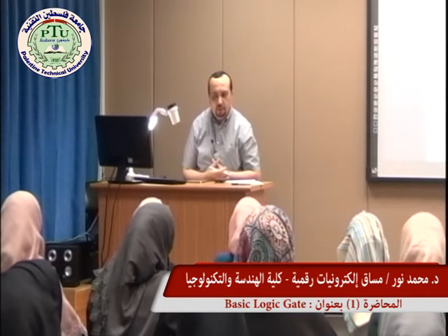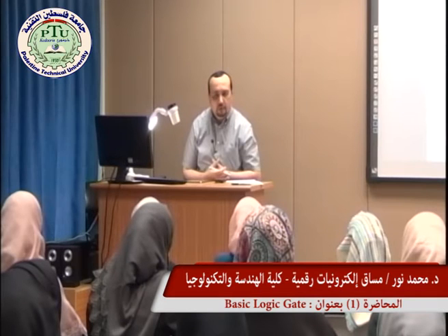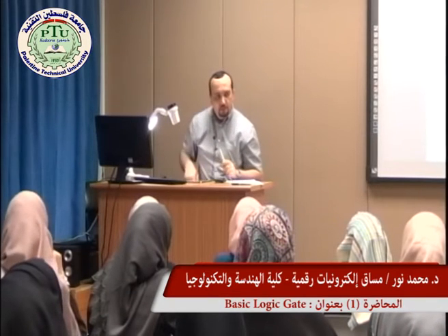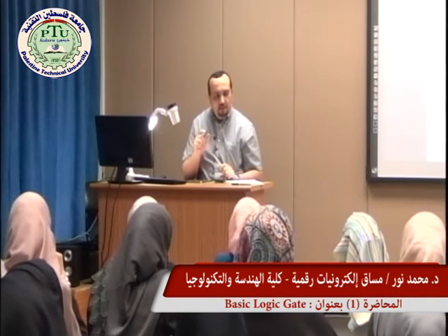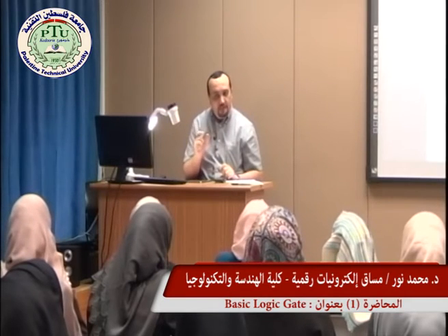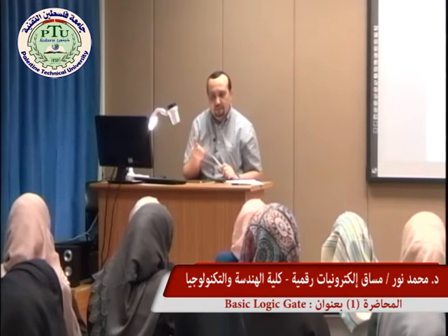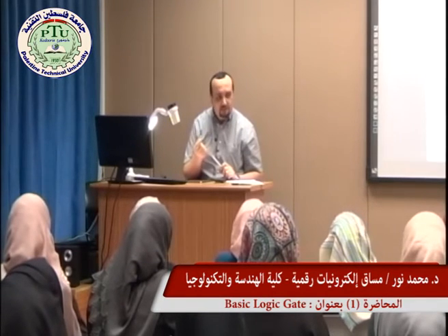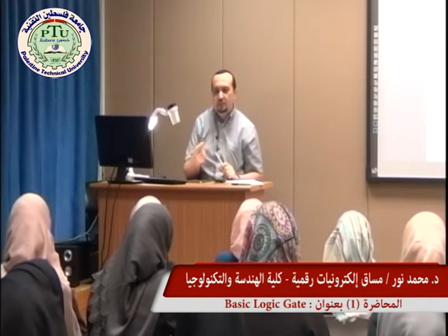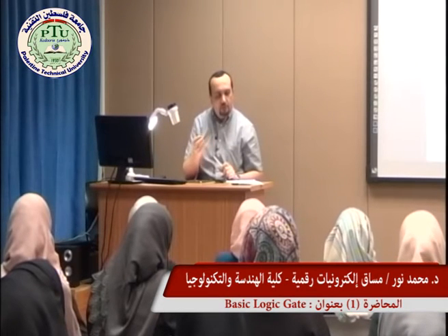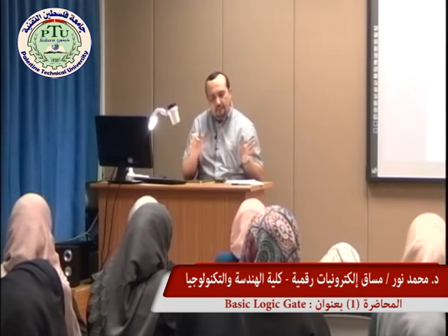And when you start to study higher or advanced classes, we can also use the transistor to store data, 0 and 1, because flash memory, if we open it up and study it carefully, is made out of MOSFET. Just regular MOSFET, of course with an extra floating gate in the middle, which is what allows it to store the 0 and 1. That is beyond the class.